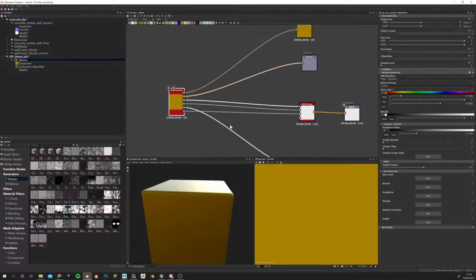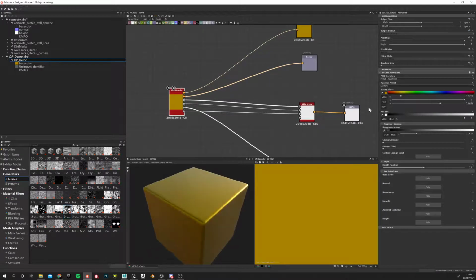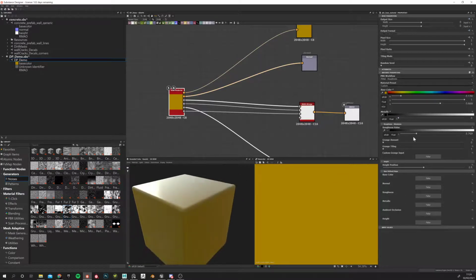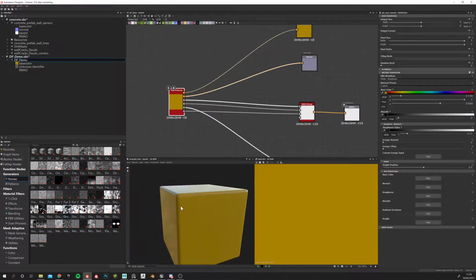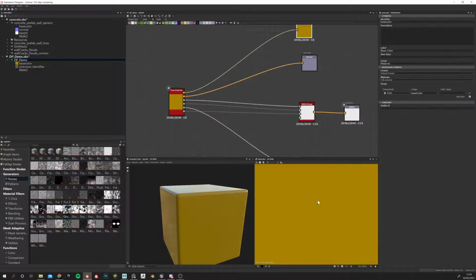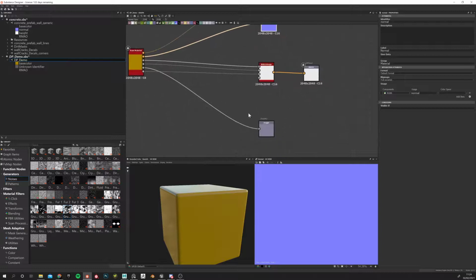At the moment we have this material, and metallic is 100%. Now, what will happen when I put metallic to 0? I'm going to put metallic to 0, and decrease the roughness, roughly like this. Now this looks plasticky, correct? Ignore normal and ambient occlusion for a moment.